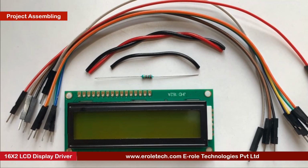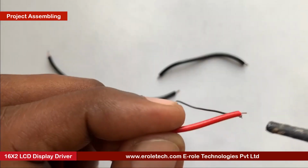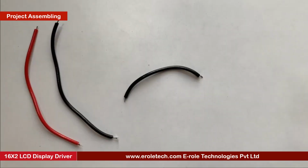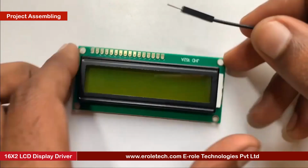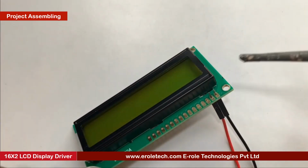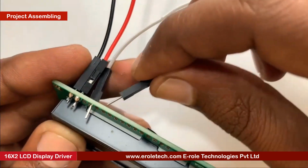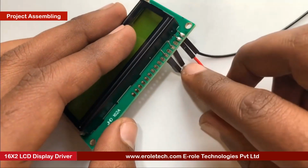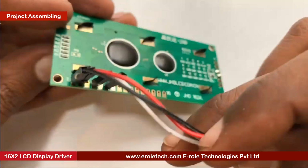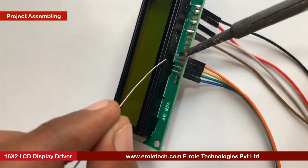Now we will assemble our hardware. We will take 3 wires, 1 red and 2 black. We will use these wires later. Now we will solder a black wire at hole number 1 and red wire at hole number 2 of LCD display. Now we will solder a white wire at hole number 4 and brown wire at hole number 6 of LCD display. Now we will solder orange, yellow, green, and blue wires at pin number 11, 12, 13, and 14 of LCD display.